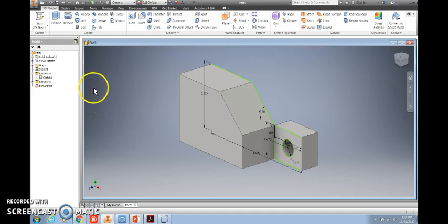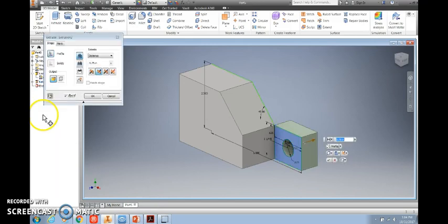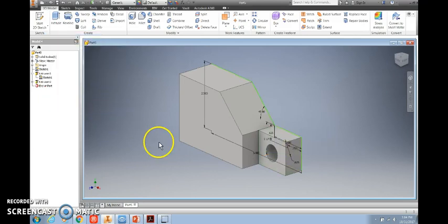Okay. And now let's try to edit that. I want to show you one other thing. So if we go over to extrusion 2 and right click on that, we can go to edit feature, and we'll bring that back the other direction now, which is how we want that to look. Click OK, and we have the overall part that we were trying to draw.